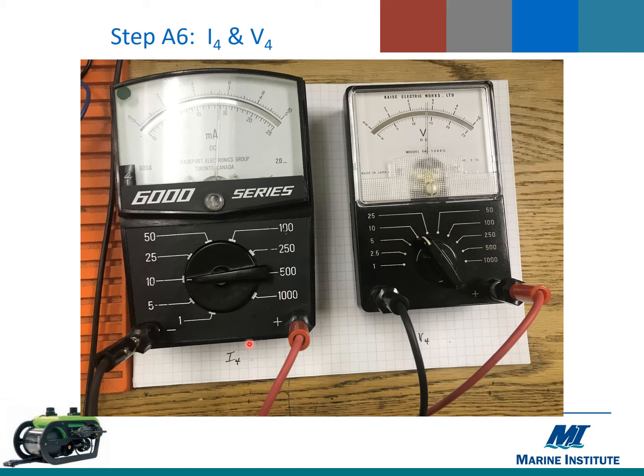Okay, for I4, then, the milliammeter is on the 10 milliamp scale now, and so again we'll go to the very top set of numbers for the scale over here. Now again, we are between 5 and 6 milliamps, and right almost exactly halfway between. And so we have recorded that current as 5.5 milliamps, which is interesting because that agrees a lot closer with the color-coded value if you apply Ohm's law than it does with our measured value of 1150 for R4, doesn't it?